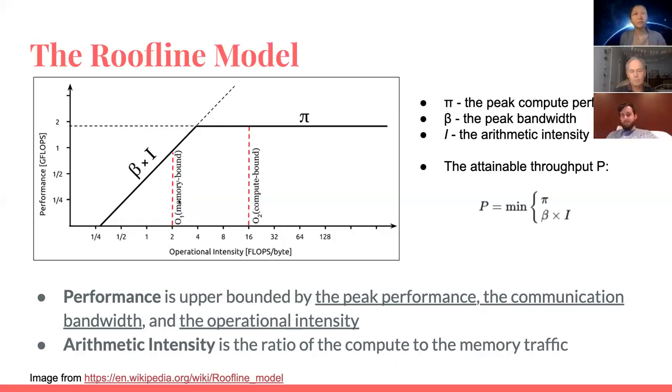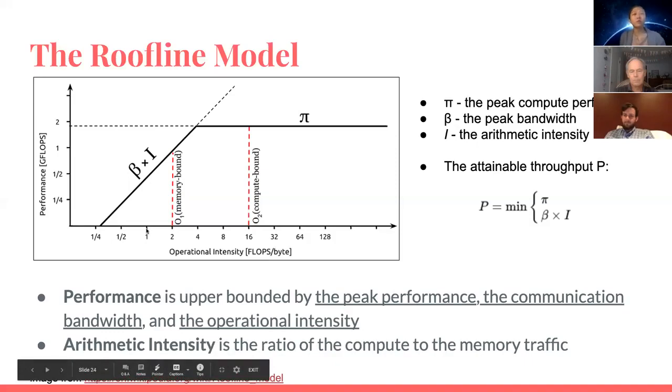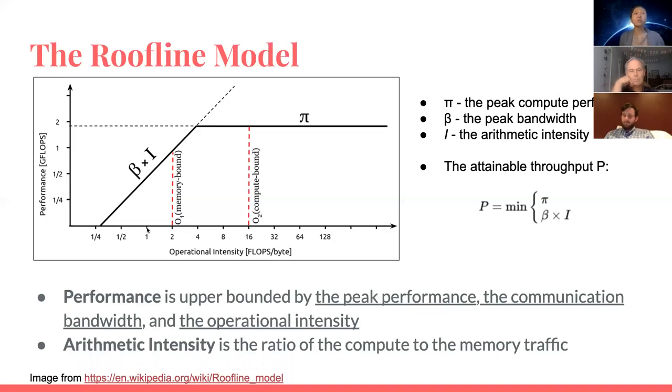And with lower arithmetic intensity workloads, for example, if we can use the weights once they're on chip only once for one multiplication, and then we need to dump them, then the arithmetic intensity will just be 1. In this case, it will be memory bound. There are two ways to improve this workload. Either you can improve the memory bandwidth to your PE so that the slope of the beta line will be steeper, so that it wouldn't fall into the memory bound region. Or you can try to optimize your software workload to make it use the on-chip loaded weights more. If you change your algorithm, you can move your point from 1 to 10, horizontally to a more efficient region with higher arithmetic intensity.